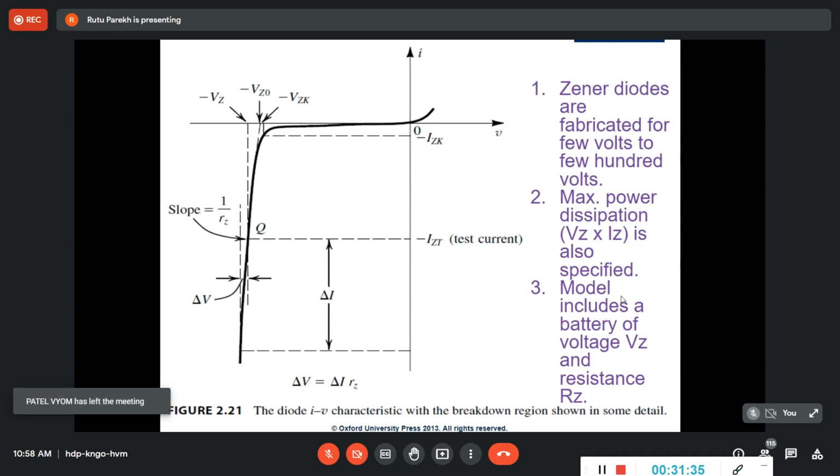Right, so what is power? P is equal to I into V. So P is fixed. If voltage is varying, current has to be less. So it has to obey that I, V or P limit. Otherwise, the component will get destroyed and you have to throw it away. Everybody has a limitation, right? The human body has a limitation. Extreme conditions we cannot take. Similarly for the device. And we had seen for an LED that if the LED is a 3-volt LED and you give 5 volt, it will get destroyed.